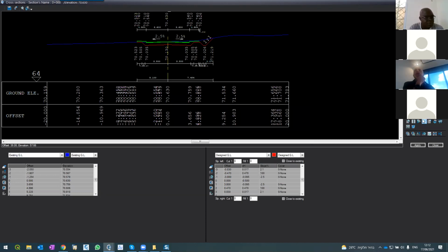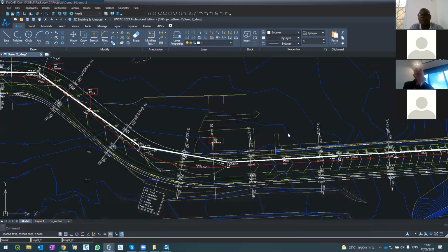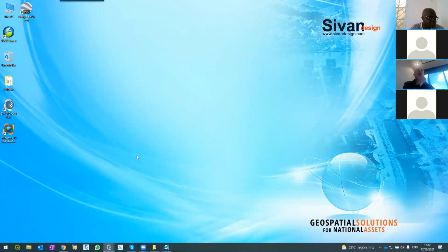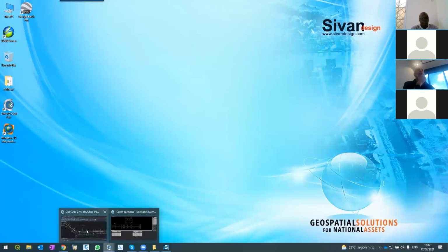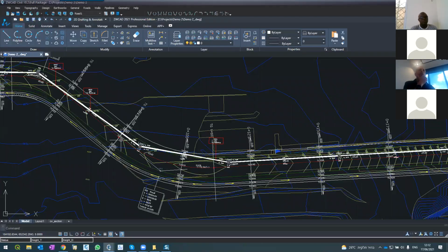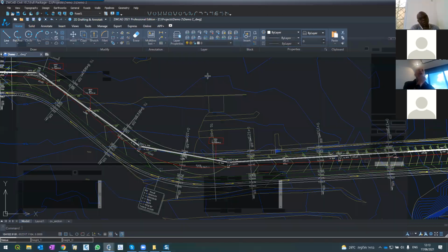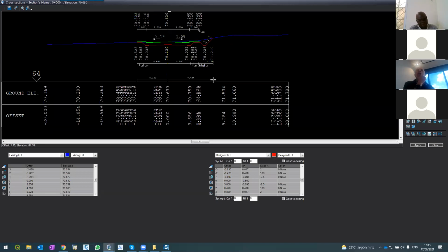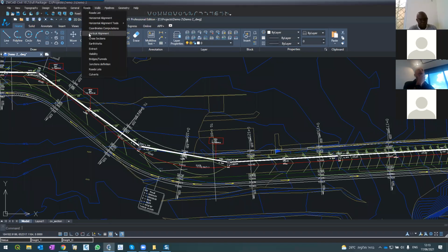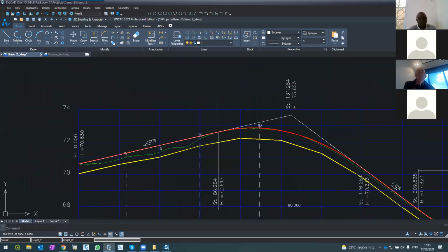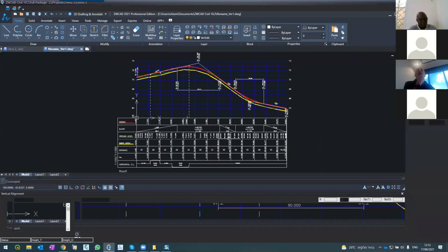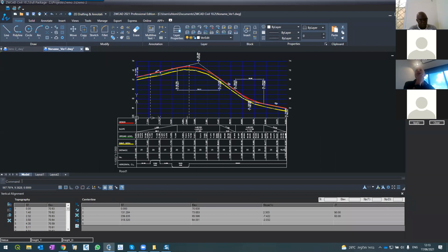Yeah, so the sewage, there's no problem, but in terms of super elevation here, it says that it cannot use the automatic super elevation, which I wanted to use. I wanted to show you because it says here the curve is too sharp, too small for it to work with AASHTO regulation, but I can design my own super elevation, and then if I go to the profile, automatically I can see them and also project them here. For now, it will not show anything.